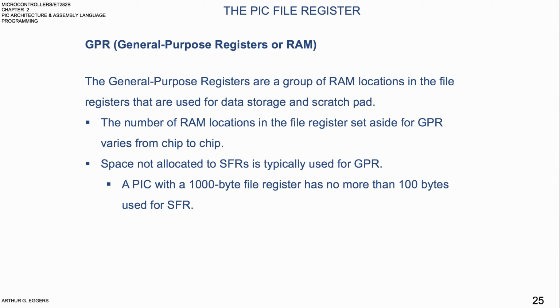A larger GPR size means more difficulties in managing these registers if you use assembly language programming. In today's high-performance microcontrollers, however, with over 1,000 bytes of GPR, the job of managing them is handled by C compilers. Indeed, C compilers are the very reason we need large GPR, since it makes it easier for C compilers to store programs and perform their jobs much easier.